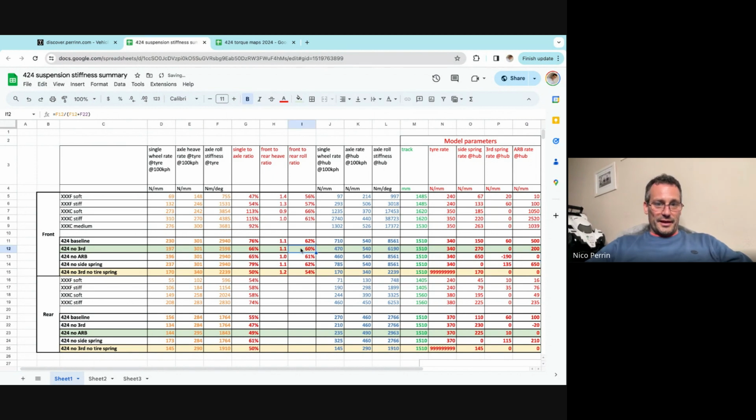You can see that my roll stiffness distribution has dropped to 60%. So that's a 2% step. At the track, we talk about these numbers as an engineer because we know a 2% step will be felt by the driver. That step will allow the driver to have a bit more grip at the front. If he complains about understeer at slow speed, you would do a step like that. Okay. I've gone back on this change.